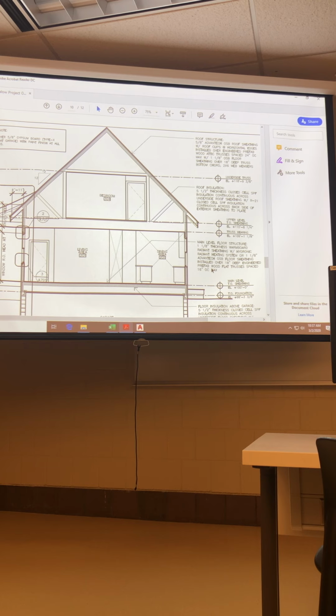It has grooves, and we're gonna see this later in the semester in 1020, but it has grooves in the top of it that we can put the tubing for radiant floor heating systems right in our floor sheathing. It's a brilliant product, it's a great product, it's just really expensive. So we're going to use that for our structural floor sheathing, but also it's going to allow us to have radiant floor heating systems.